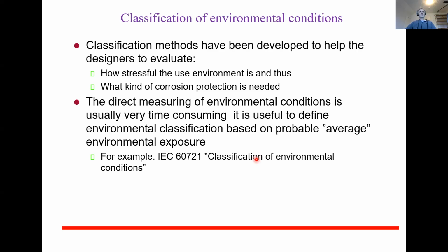So a simple or relatively cost-efficient way, which is used really frequently in industrial electronics, is to use conformal coatings. So this is one topic for the second assignment. Conformal coatings are just, for example, lacquer, silicones, polyurethanes, or whatever, which you apply on top of your printed circuit cards. They are not completely hermetic, but they slow down the diffusion of moisture and also impurities. And that's the reason that they will improve the reliability.